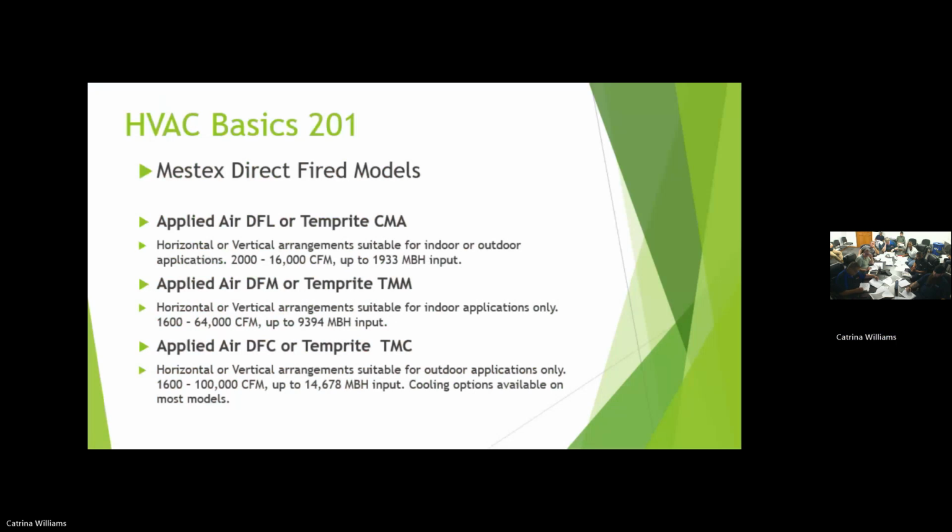We have evap cooling that's good all the way up to 100,000 that we can add. We have DX and chilled water that peak out about 50,000 only because the coil gets so big, we can't ship it. Coil's just that big. You think at 100,000 CFM at 500 feet per minute, we'd need 200 square feet of big box.